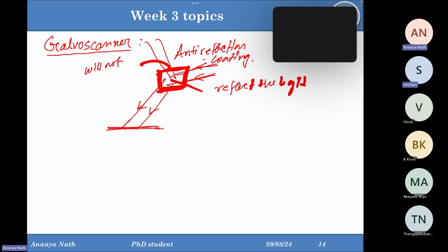If we are talking about multiple mirrors, then I'll attach multiple mirrors to a CNC head, and command the CNC using G code and M code, like you should move these mirrors to this position for this layer, and tilt these mirrors, like A B C D E F, only these four mirrors at 45 degrees, to project the light over the substrate for the n plus 1 layer.